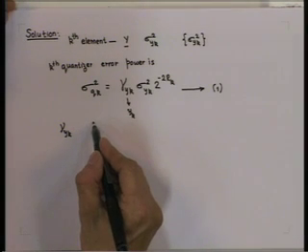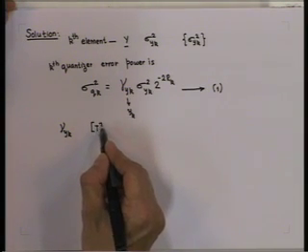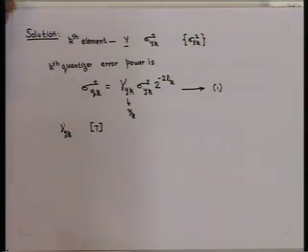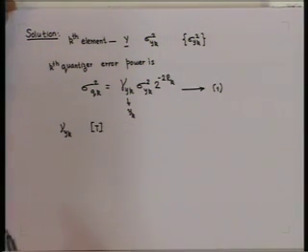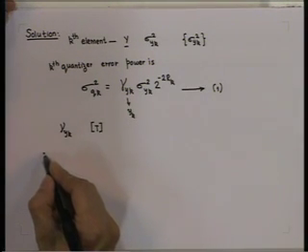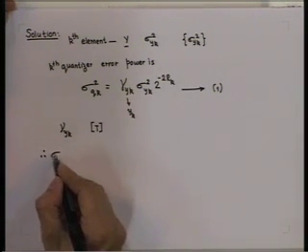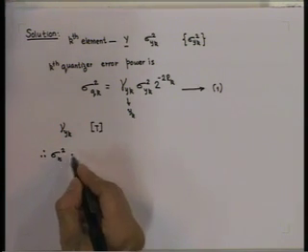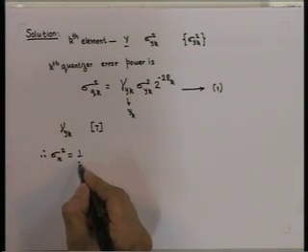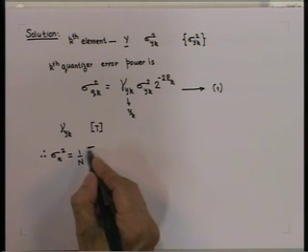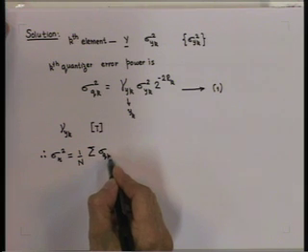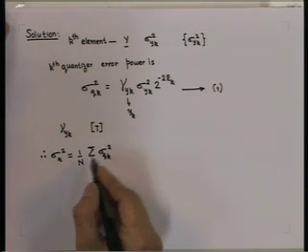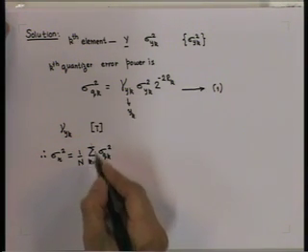Because we are using an orthonormal transformation T, the mean squared reconstruction error equals the mean square quantization error, and therefore we can write the mean square reconstruction error as 1 by n summation of the mean quantization errors from the different quantizers.